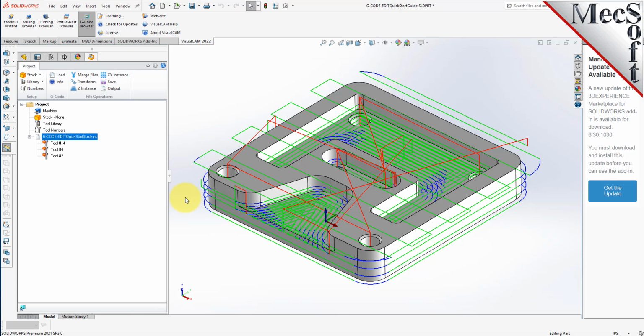That's because in your tool library, you may have multiple tools with the same tool number. In your shop, you may have hundreds of tools, depending on your standards and the way you apply your toolpaths and your tools. You may have more than one tool with tool number 1, say. So you define a tool crib with a subset of those tools in the library, and assign the tool numbers to those tools. How they appear in the tool crib is what will be selected from when you load a G-code file that references tools.